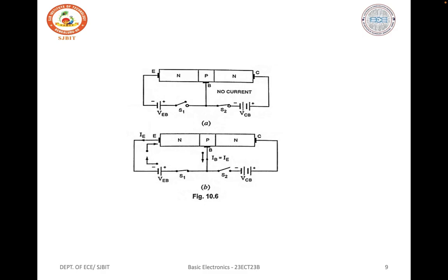negative on the base. Typical transistor base emitter voltages are similar to diode forward voltages, 0.7 volts for a silicon transistor and 0.3 volts for a germanium device. Collector voltages might be anything from 3 volts to 20 volts for most types of transistors.